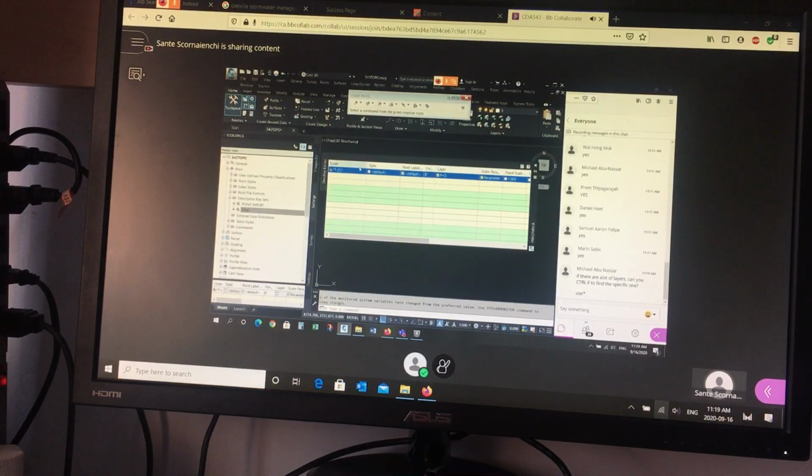So you're going to have 10 lines of code. Another one was edge of pavement, remember? So in here, to create another line, you can't just click in here. To create another line, you have to right-click and say new. That's the way it works.